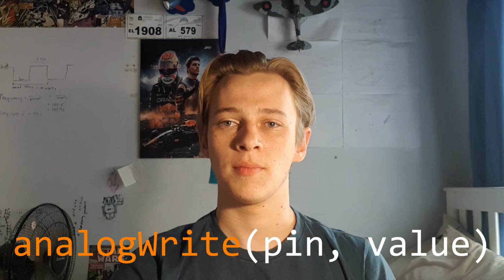While Arduinos do not automatically output PWM, one can use the analogWrite function to output PWM signals to certain pins at a fixed frequency, which is normally around 490 Hz. And so, to properly answer the question I know you're all begging to be answered, an Arduino can output PWM signals if it is coded to do so.